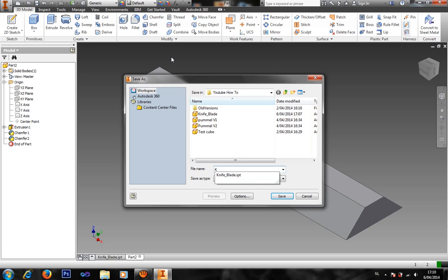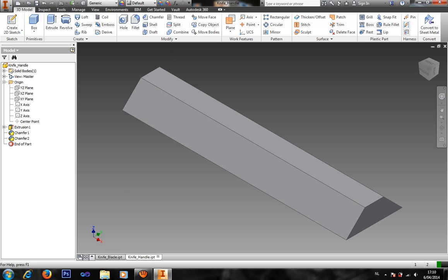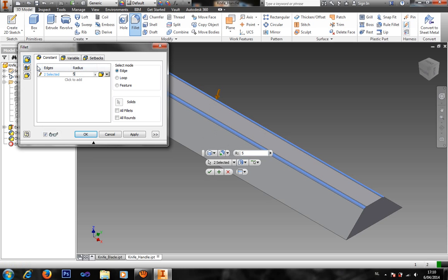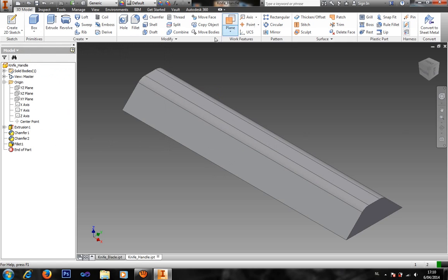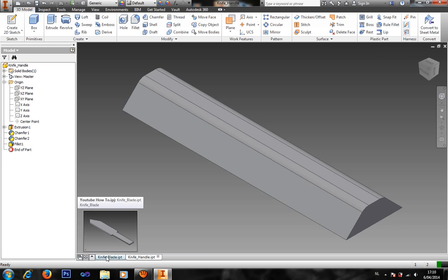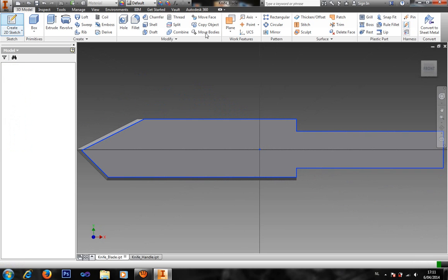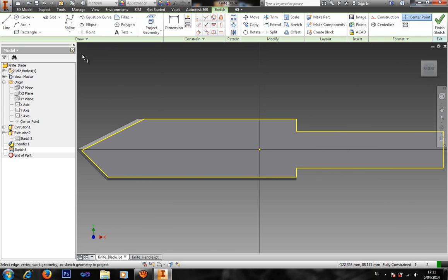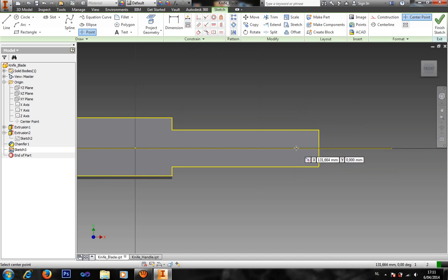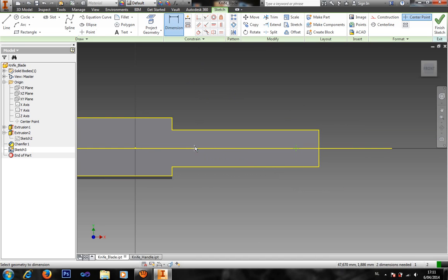We could, and I most likely will, refine the shape. Okay, some more decent shape. So we got the knife, we got our handle. Only thing left is we need some holes drilled. So we all know how to do that. Obviously, you all have been paying good attention on our other tutorials, so we all know how to make holes. Distance, that's a fairly good distance, around 80.